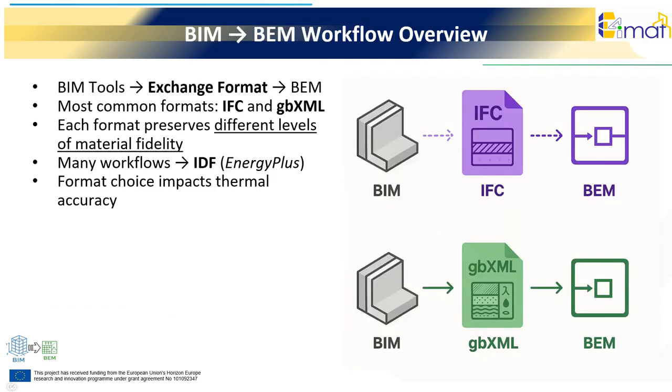Before diving into the specific formats, it is helpful to understand how information typically travels from BIM to BEM. Most workflows rely on an intermediate exchange format that acts as a bridge between the BIM authoring tool and the energy simulation platform. In practice, the two formats used most frequently are IFC and gbXML. Each one was developed with different intentions, which means they handle materials and constructions differently.